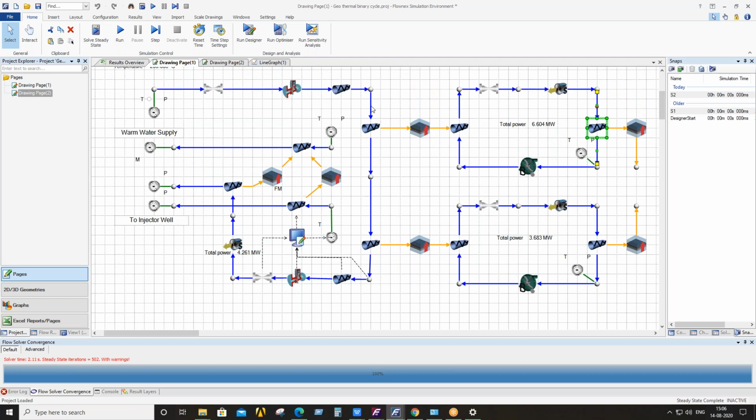And you can see that after heat exchange in the Hexane cycle, the quality of the steam reduces. Here you can see the quality is 1.04 and the temperature 200 degrees Celsius. After the first heat exchange, it reduces to 0.78. It means the dryness fraction reduces and some liquid comes into the steam, and it becomes a steam-water mixture.